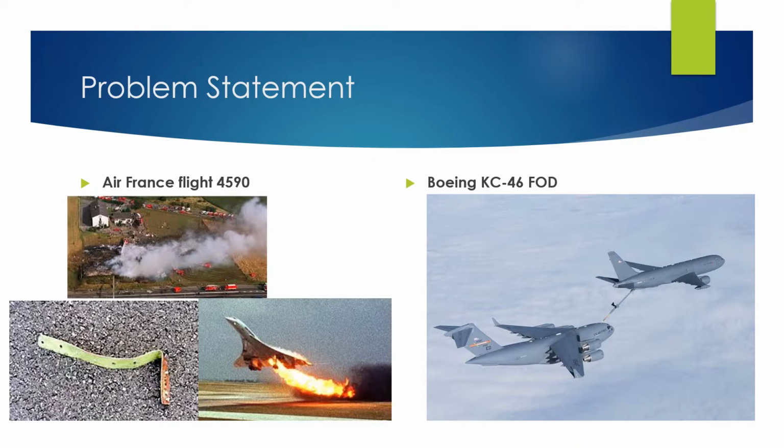The Continental maintenance department failed to complete an airworthy repair, which led to the FOD dropping from their aircraft and being left on the active runway. Continental Airlines was found responsible for the crash in court, ordered to pay Air France €1 million in addition to 70% of the compensation claims. It was revealed that an irregular repair had been made, not using an original equipment manufacturer's (OEM) parts.